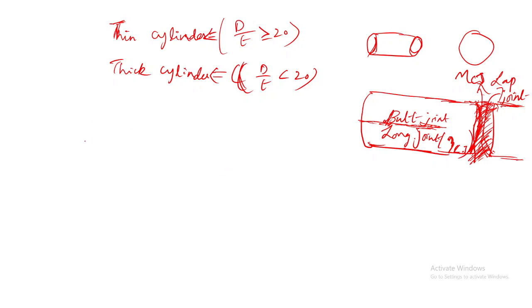Up to this it is clear? Yes, sir. So if I want to find out what will be the stress, inside there is a pressurized fluid which is exerting a pressure in all directions. Imagine this is a cylinder, so you should not imagine only the pressure acting towards this direction, but also circumferentially, towards this, this, this, and all through the circumference it is acting. That's the point I want to make.